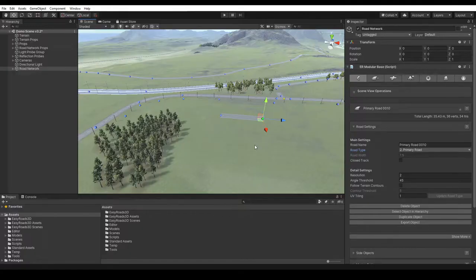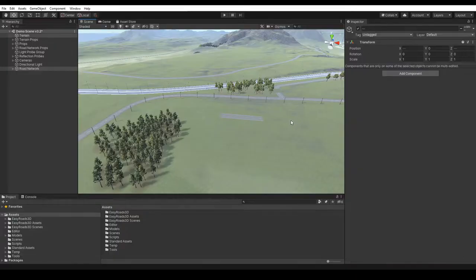The road properties are visible in the inspector. One thing that may need attention here is the state of the Gizmos tab on the right above the scene view window. The Gizmos tab should be active to show the marker handles. This tab will be active when using the default Unity factory settings, but you may want to check this when no marker handles are visible. In fact, this Gizmos tab in active state seems to interfere with Unity events, the shift-click event in this case. After shift-click, the terrain will also be selected. This is the default Unity behavior when clicking an object in the scene.